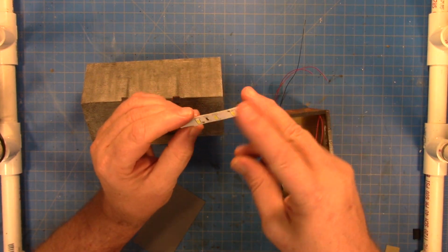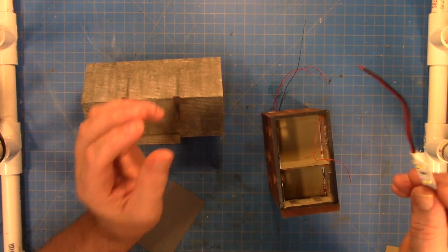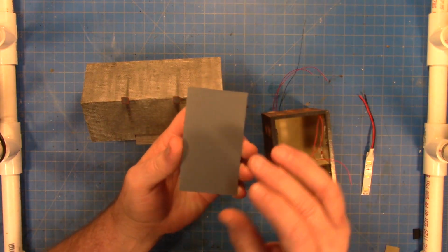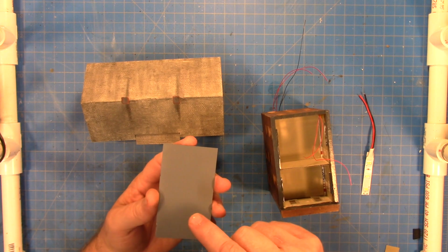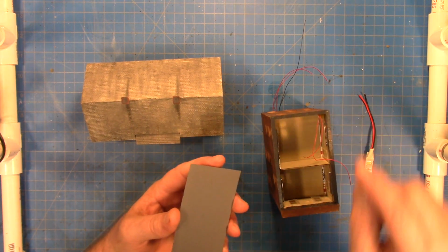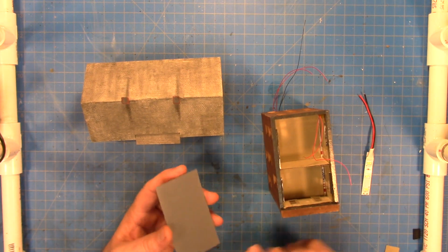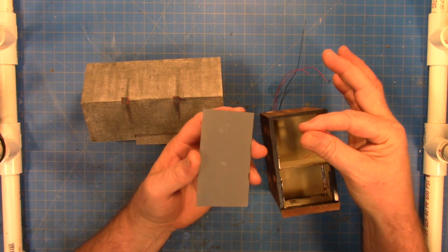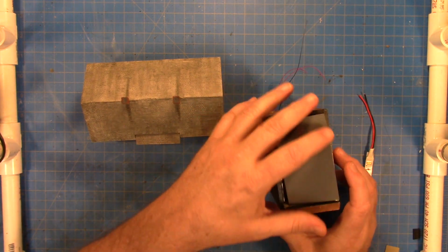The one I bought, they're designed to be cut into individual LEDs. So they have double-sided tape, so I'll stick 2 of those onto here. I will wire the negative connection of one to the other, and then take a wire down through that will ultimately go down to the common. We'll see in a second. And then obviously the 2 red wires will connect to the positive leads. We'll do the same thing.